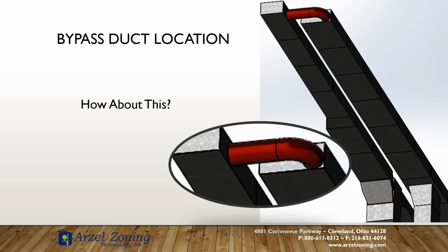Another application, and there are some zoning companies out there that recommend this. We don't, and the reason being is that on your supply side, the end of your duct is the point of your supply duct that creates your back pressure. That is the highest point of pressure in your supply duct that allows you to actually pressurize your supply and force your air through your branch runs, which is also why in any duct design class, they will strongly recommend you never come off your end cap. You always make sure you're at least 12 inches back from your end cap.